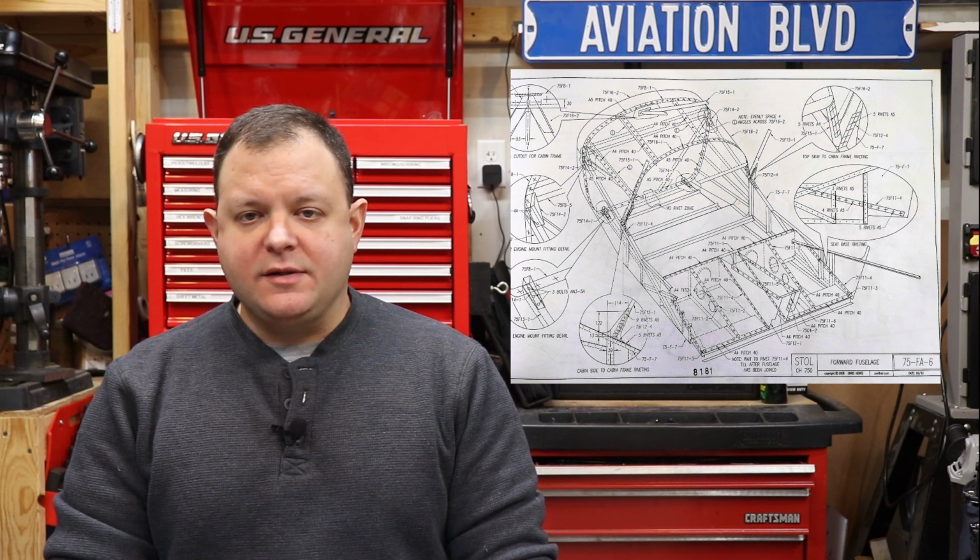When you first look at a set of blueprints, they can seem overwhelming due to the amount of information they contain. A good set of blueprints contains various types of drawings that depict complete information on parts dimensions, material specifications, hardware sizes, and assembly. The information should be complete enough to allow you to fabricate each component of the aircraft from scratch, and specify which standard hardware like nuts, bolts, and manufactured components are required.